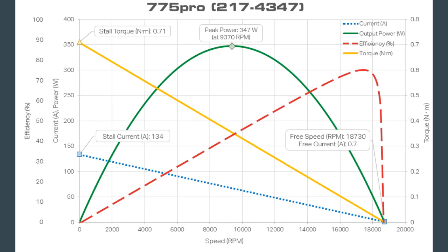So these motor curves are given a certain situation. You can think of it either way, honestly. You can think of it, given it's going a certain RPM, how much torque does it have? Or given a certain torque, how much RPM is it going to be going at?